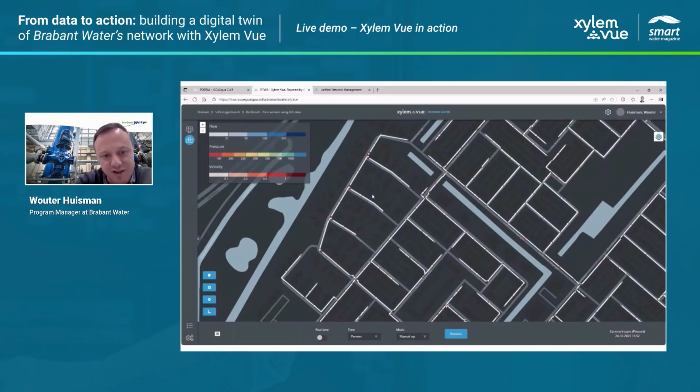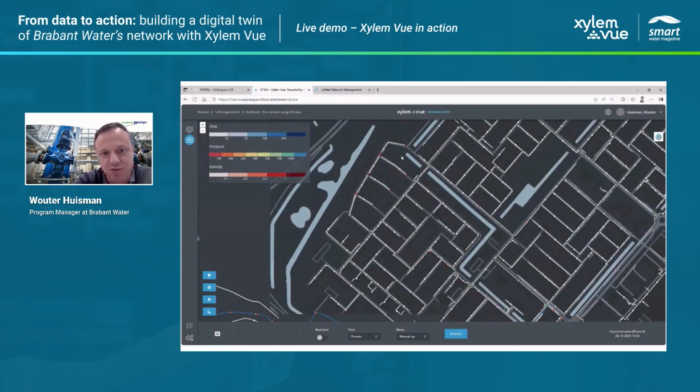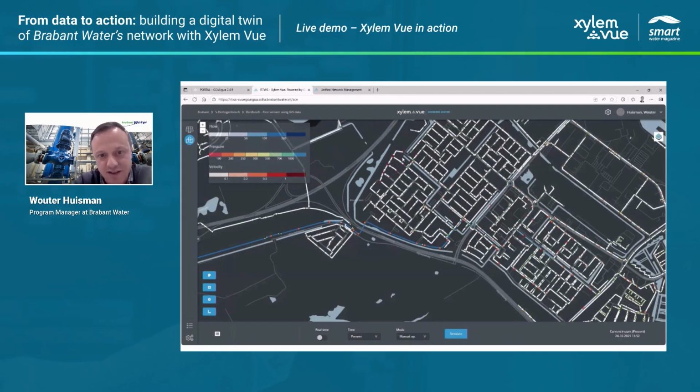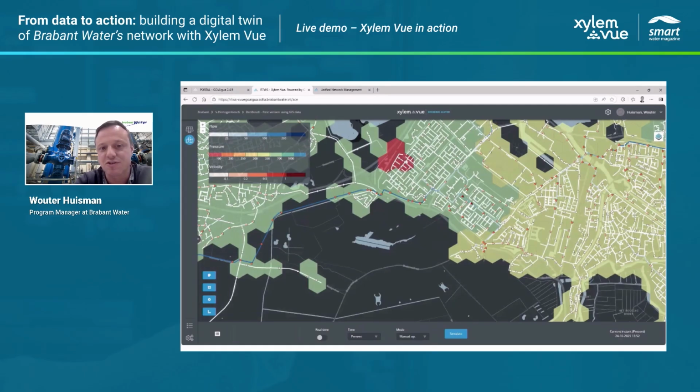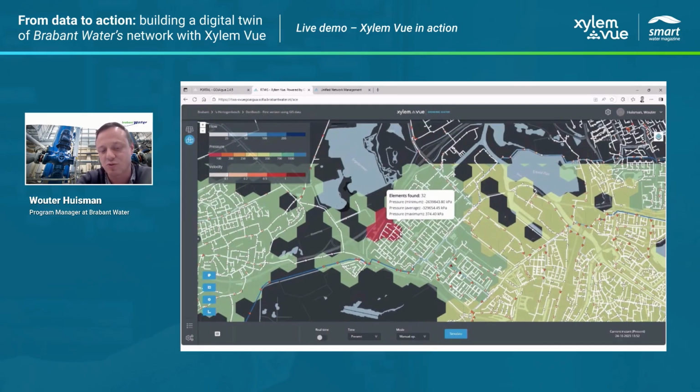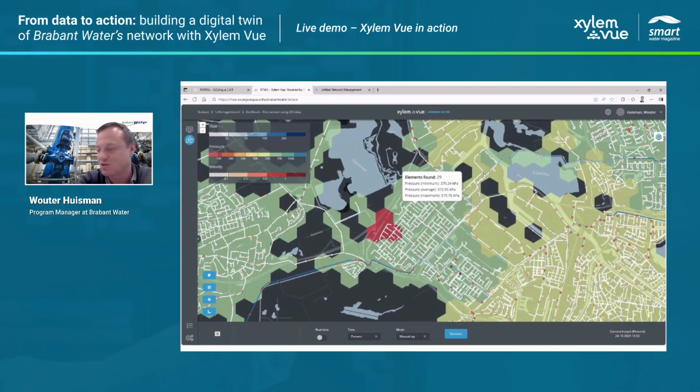and you can see already the dots, the nodes in the hydraulic model have turned red. So there is no pressure there. And if you zoom out, you have a quick overview and see that there is something wrong there in the network.